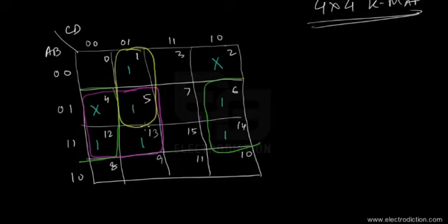Now all the valid elements, that's all the ones that we have here, have been covered in groups, and this one don't care element in cell number 2 just stays there alone. It's not a necessity to group it up because we have all the ones covered in the groups. So it's not necessary at all to include this don't care element, and we won't include it and increase the number of groups unnecessarily.